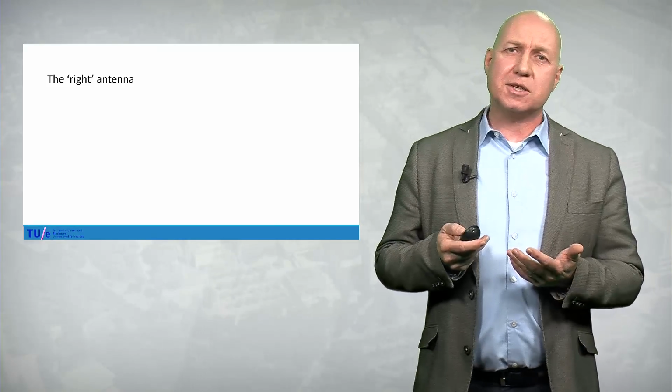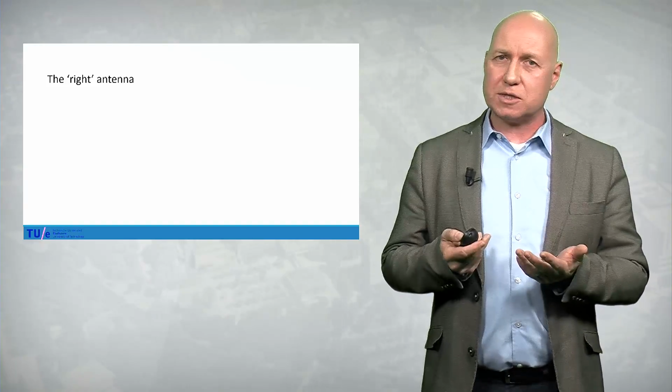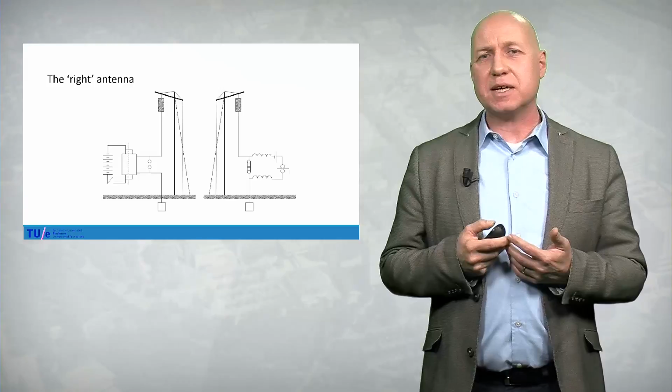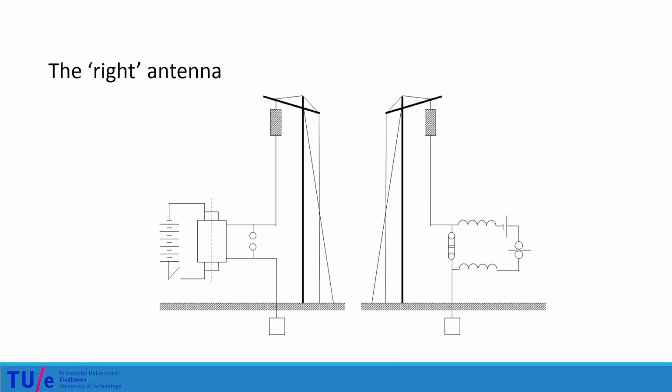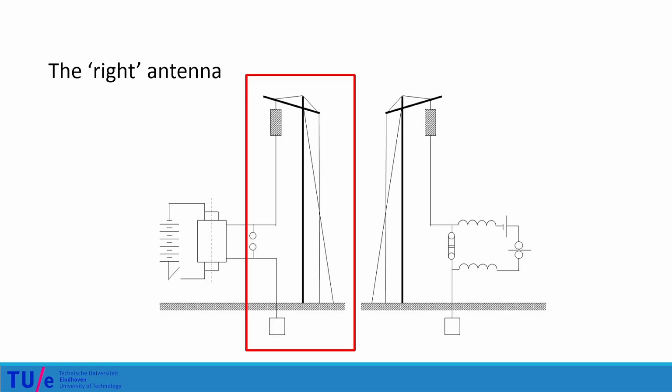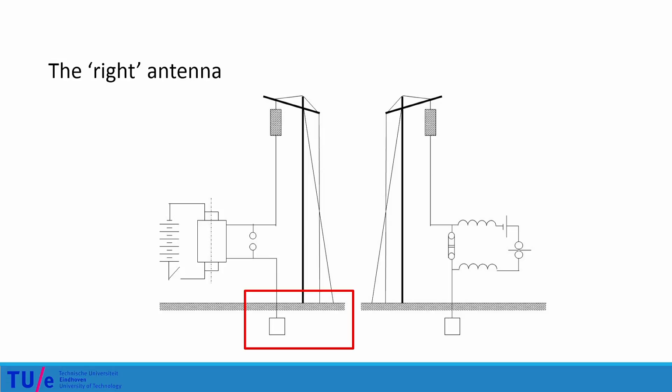And later, during a speech he gave at the reception of his Nobel Prize in 1909, he showed this picture and he explained that his success started by finding the correct antenna. What he used later was what was called in those days an elevated wire. So here we have the transmit antenna. This is the elevated wire. And what he soon found was that instead of using a whole dipole antenna, he could use half a dipole antenna, which we call a monopole, have a ground connection of a spark transmitter, and the image in the ground would form the other part of the dipole antenna.